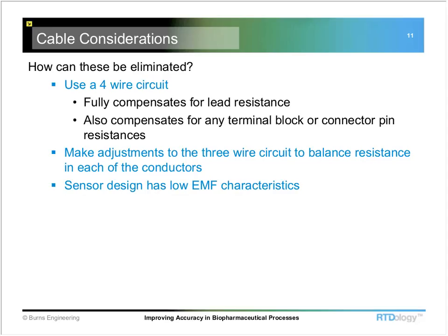So if you do have a sensor that has a long extension cable on it, look for a label like that. And if you've got 30 feet of 22 gauge cable on an RTD, and there's no label and there's nothing that says that it was ever balanced, that should maybe raise a red flag, and you check that just to make sure that it still falls within the tolerance that you're expecting it to be at.